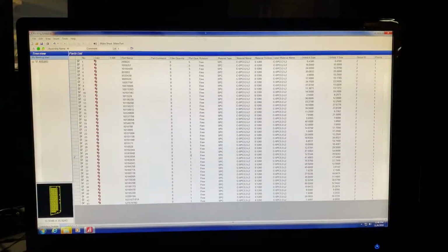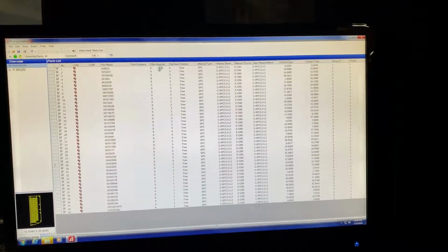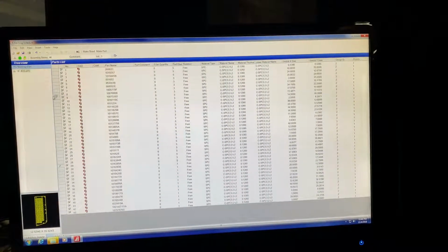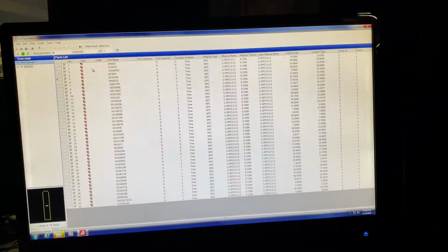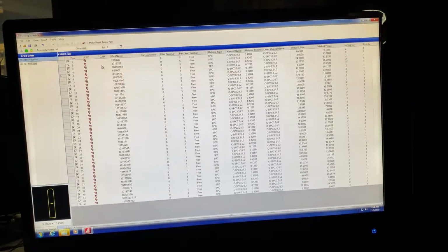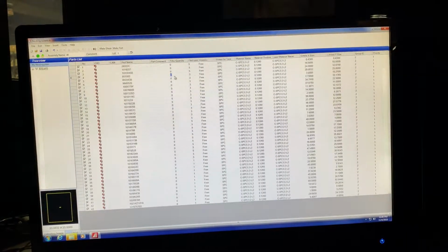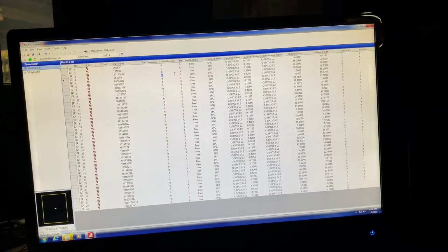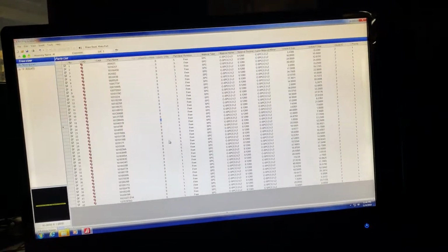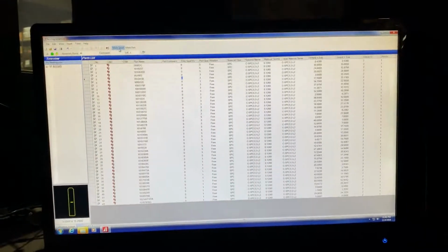And once you got your parts quantity and everything filled in, you also have filler parts quantity. So if you have a small part that you know you're gonna need more of and you want to cut more just in case, you want to cut more just to fill up the rest of the sheet, you can select how many you want of that part file to fill in the sheet for each individual one if you want, just to fill it up. Once you got that, just click on Make Sheet.